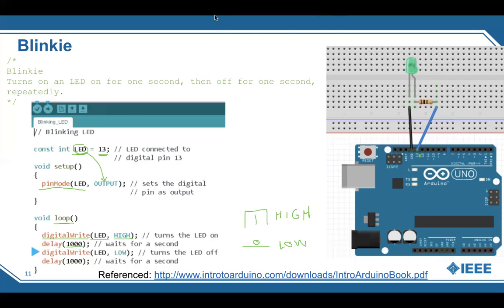And so what happens through this code, I'm going to run through it from step 1 to the very last step. Here in the first line is a comment with 2 slashes, and then you can comment what you want to do. You can see they had lots of comments, 2 slashes, then their comment all throughout here. After they had a comment for the project title, they declared a constant integer, basically a variable that won't change, and pin 13 is going to get assigned to LED.